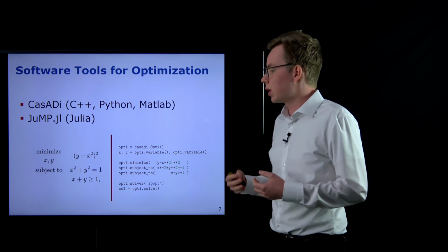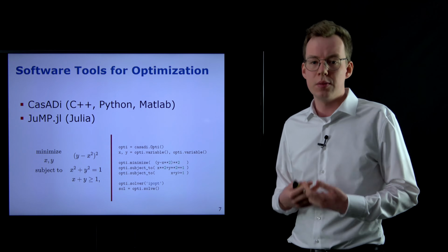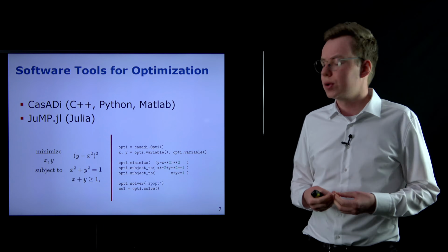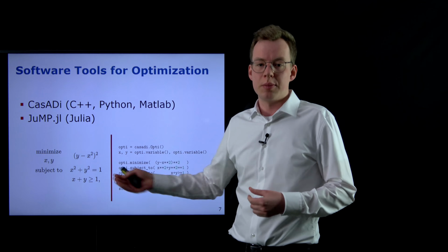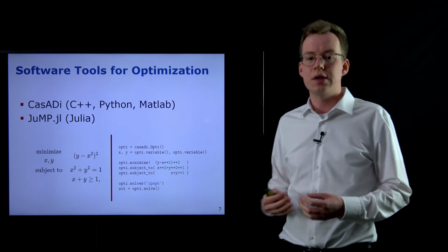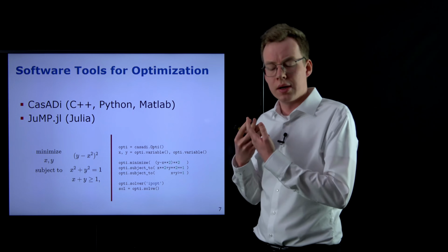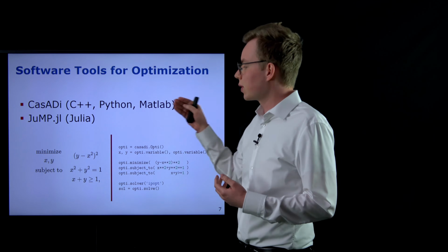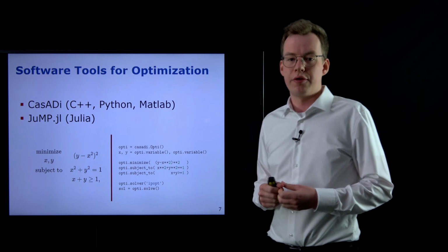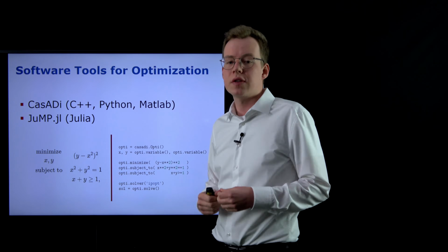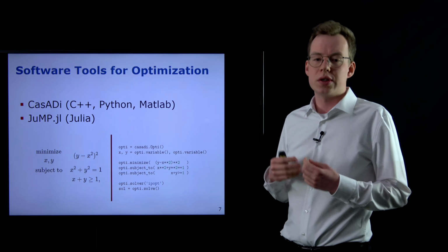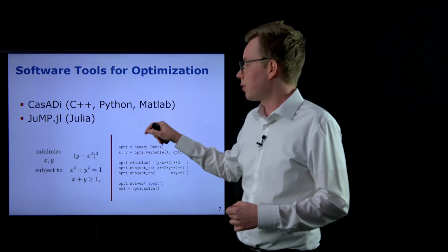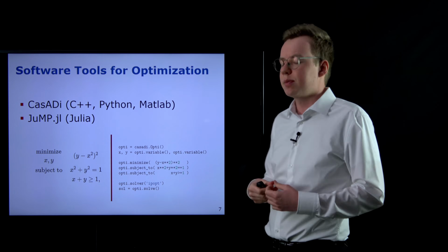In our previous lecture, where we discussed the high-level idea of MPC, which you can also find on this channel, we just assumed that we have access to some software tool to solve this problem. That lecture focused on how we can write a given control problem as an optimization problem. Once we have that formulation, we can hand it over to one of these libraries, for example, Casadi, which is a numerical constrained optimization library which has interfaces for C++, Python, and MATLAB.